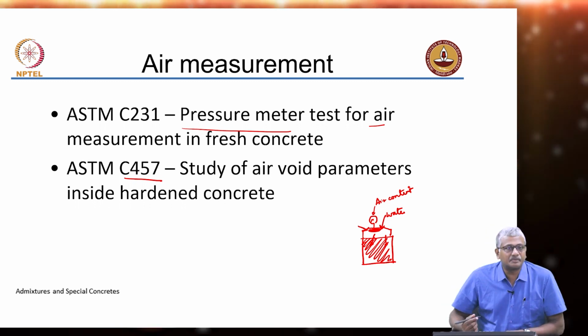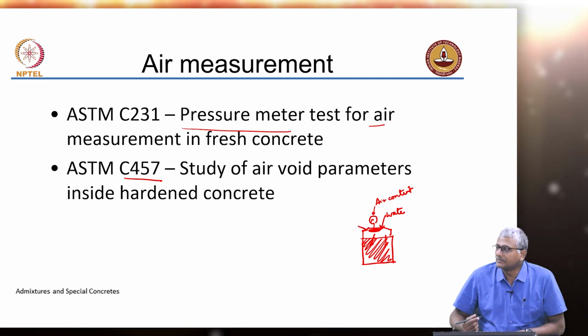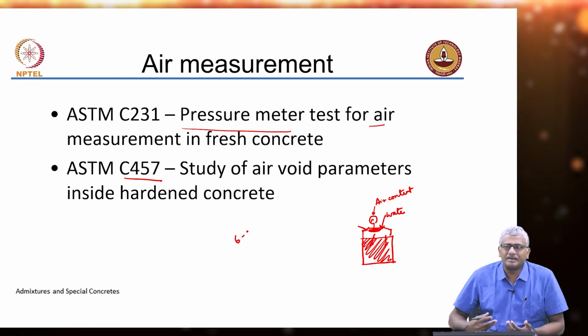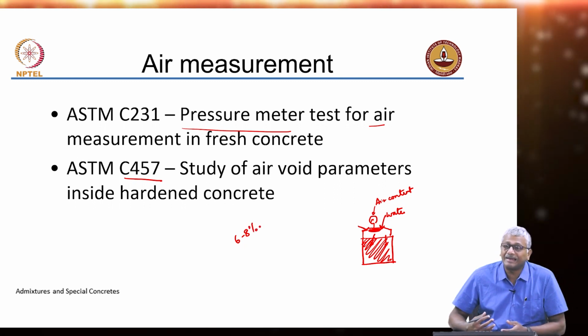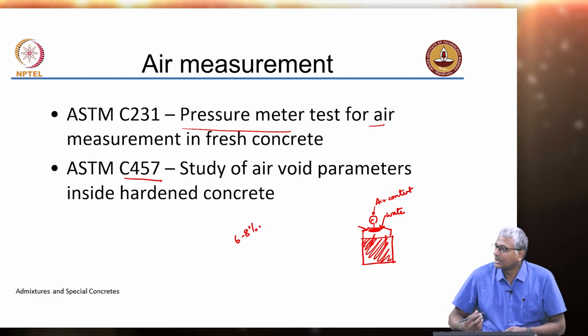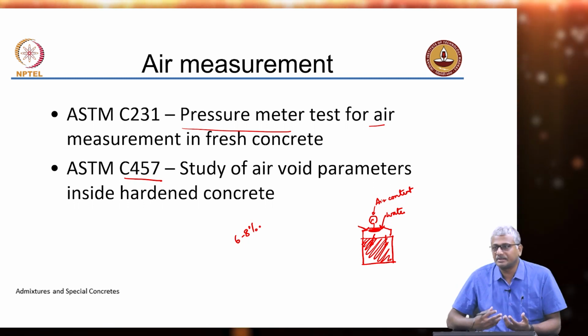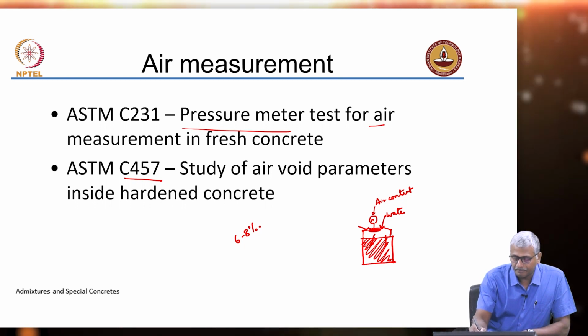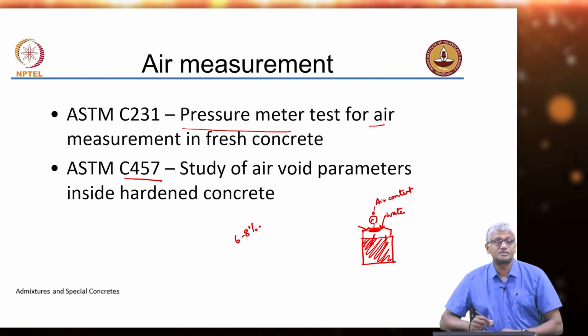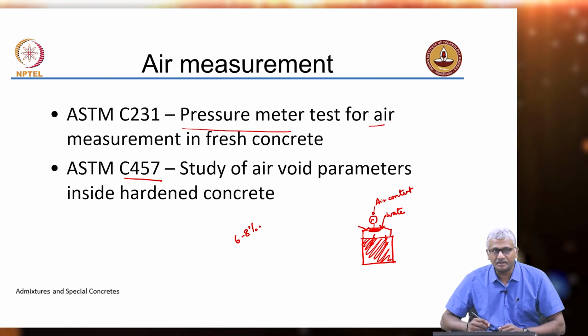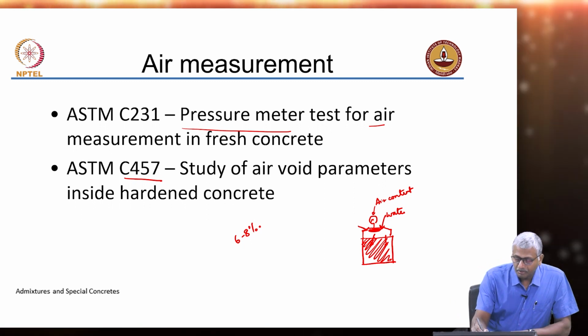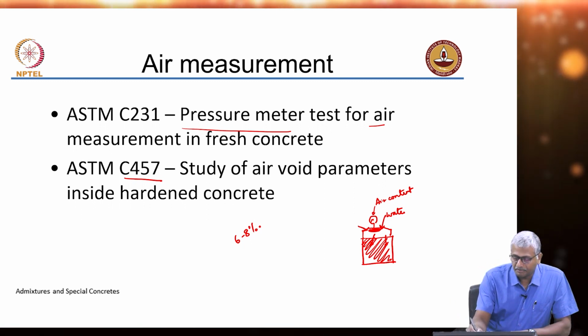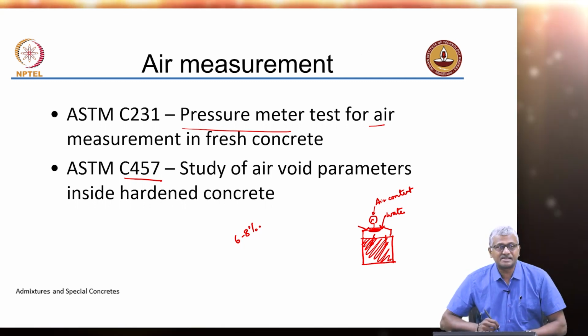How will you increase the strength of cement? You increase C3S, right? Any other way in which you can increase the strength gain rate of cement? You can grind the cement finer, right? So, more C3S and finer. And then you have type 4, which is low heat of hydration or low heat cement. So, obviously here, lower C3A and C3S. And type 5 is sulfate resistant.